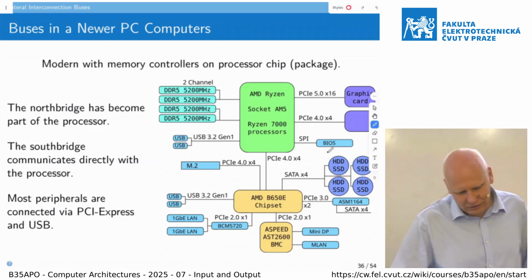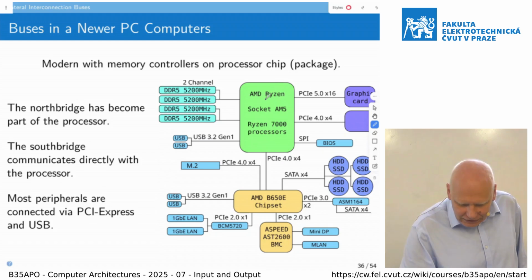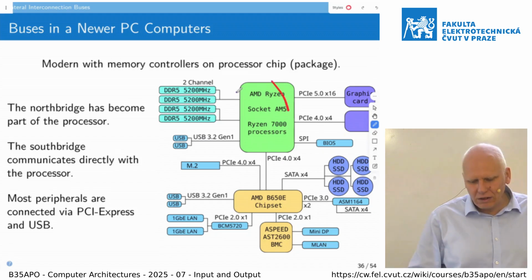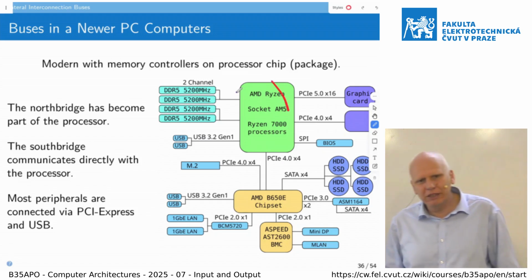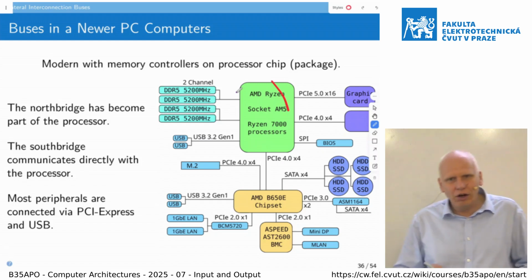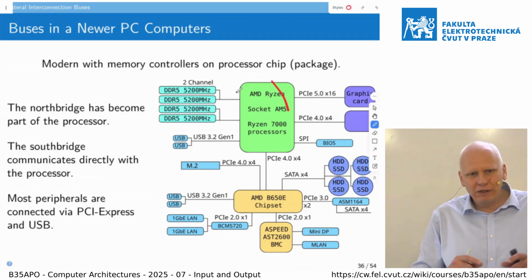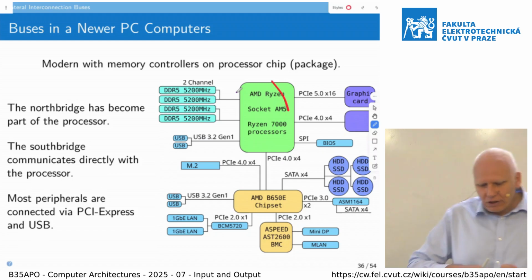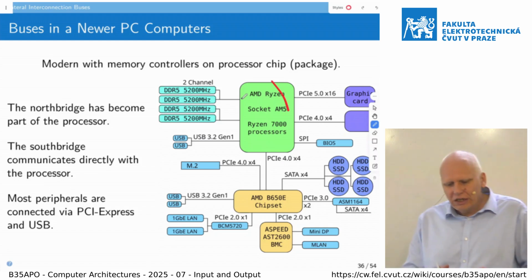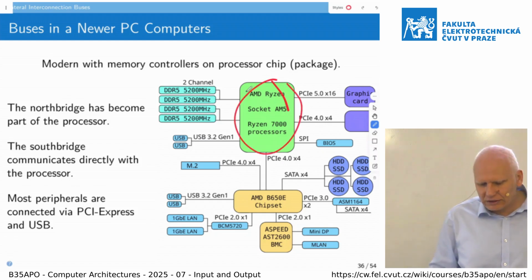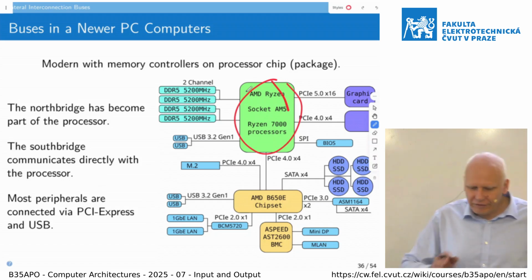Today, if we skip the development to Ryzen or contemporary Intel systems, then the memory controllers are integrated directly on the processor chip or in the processor socket, because maybe you know that the AMD is not a monolithic chip, but it is a set of chiplets with individual groups, about 8 cores, which are then soldered on the interposer with some connection where low integration I/O chips and other stuff is in the single package which you connect to the socket.